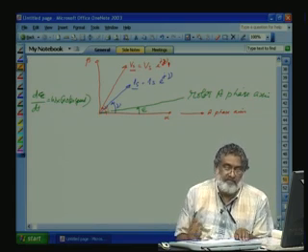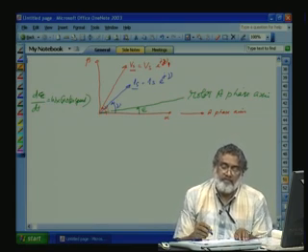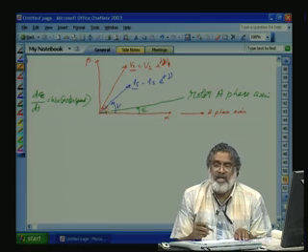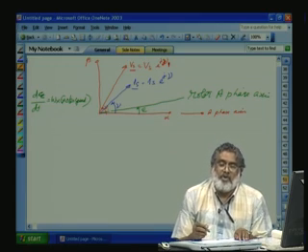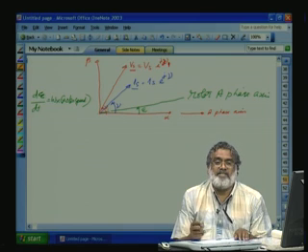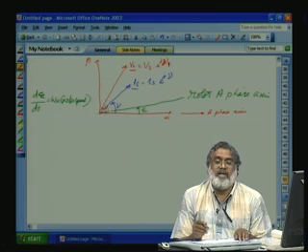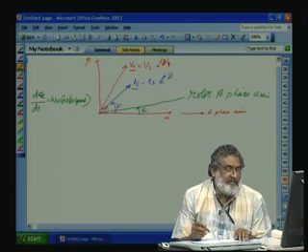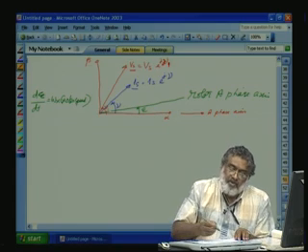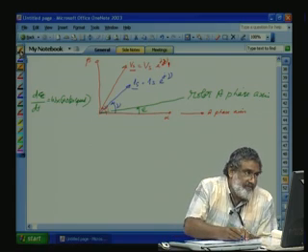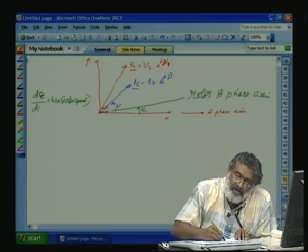Okay. So, the rotor also has an ABC axis. Suppose we measure the rotor current with respect to the rotor ABC axis, the angular velocity of the rotor current space vector will be proportional to the slip frequency. So, let us say there is a rotor current IR.